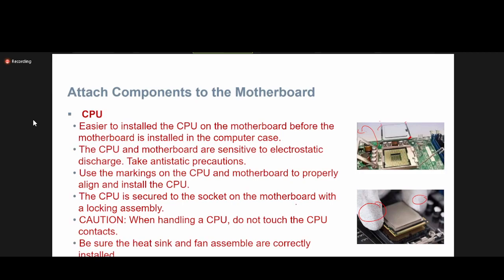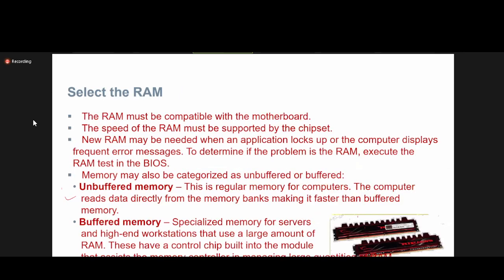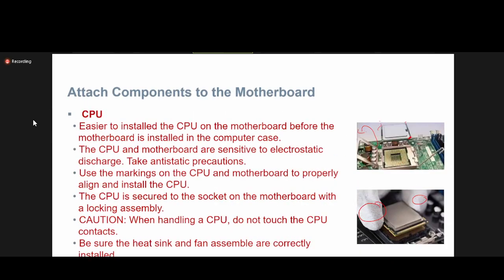Caution: when handling a CPU, do not touch the CPU contacts. Do not touch this side. This side is the contact side, because you may pass ESD through your hand to the device and it may damage the device. Be sure that the heat sink and the fan assembly are correctly installed.